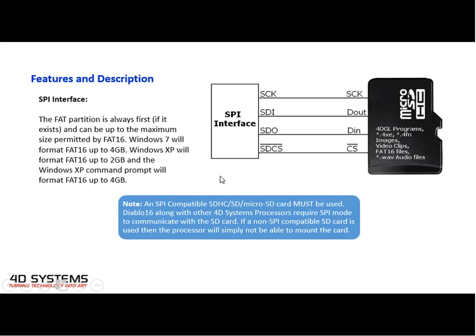Okay, the SPI compatible micro SD cards must be used. And we are using this protocol. We are not using the normal SD protocol, much as we want to, but this, since we have limited resources as far as having this all embedded, so we suggest that the micro SD used must be SPI compatible.